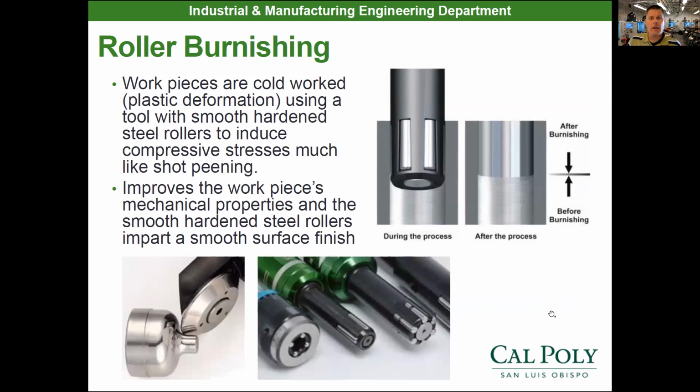Now, another one is called roller burnishing, or burnishing, technically. So this is more plastic deformation of your workpiece. Remember, whenever we're cold working something, we're making it stronger overall to a certain point, right? But sometimes you cold work it too much, so we put too much stress in the part and it's no longer strong. However, when we're talking about roller burnishing here, which is a surface treatment process that's usually done on a machine tool,